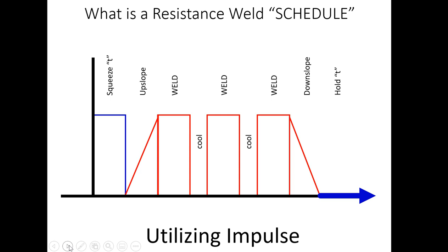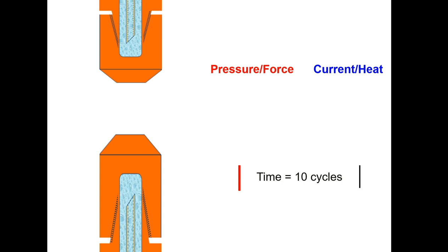So what we do with resistance welding is sometimes we'll run extra impulses and then adjust this cool section here. There are some cooling phases here. If I make these wider, I can get more of an annealing effect. If I make them much shorter, I can get a tougher effect. So my weld outcome can be drastically affected by the application of hot and cold. We need to make sure, based on the material we're using, that we get it right. Watch for embrittlement, especially on some of these HSLA materials.